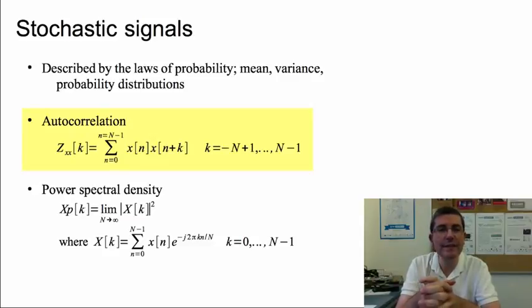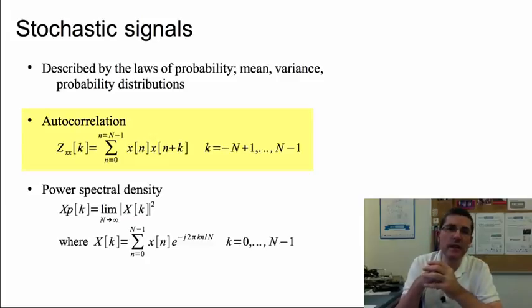We use it for detecting the fundamental frequency. So this is a function that can be used to measure how stochastic a signal is. If there are no repetitions, that means that it's going to be close to a stochastic signal. So the lower the autocorrelation function value is, the closer this signal is going to be to a stochastic signal.